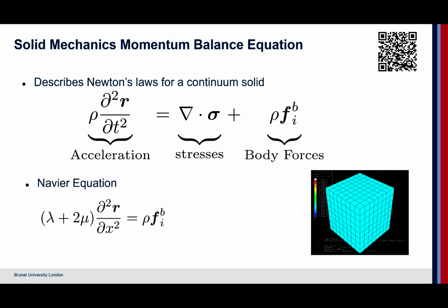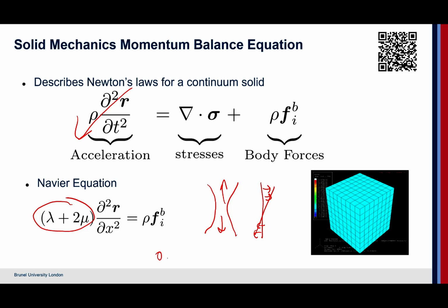For solid mechanics, one of the things you can do is, if you have zero acceleration for this term, you can rewrite the stresses in terms of coefficients, Lamé coefficients, and write an expression for a test piece here. So you can think of cases where you're stretching a test piece, and you could imagine plotting the extension as being a linear solution based on that. Or the case maybe where you've got some form of pinned beam and you're bending it in this way.